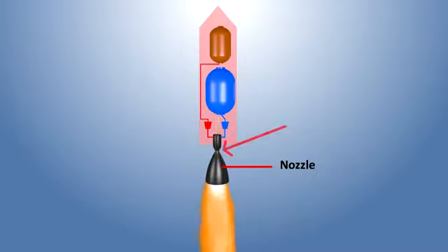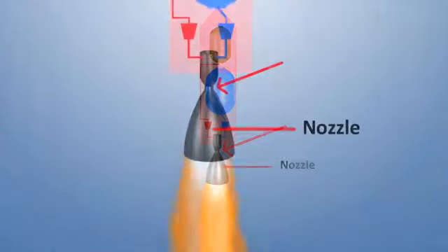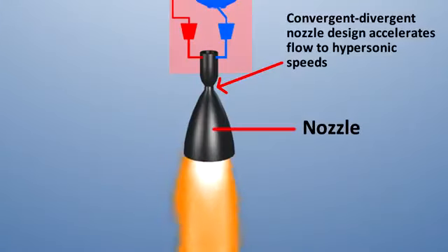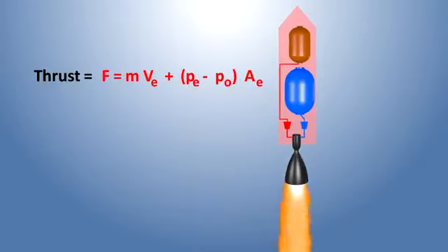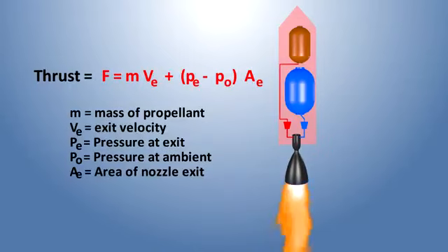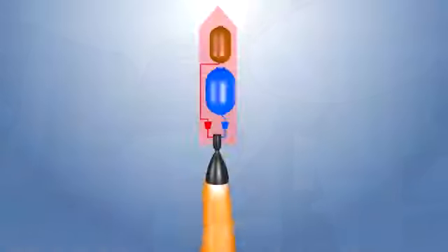The shape of the nozzle of the rocket is designed to increase the velocity of the exhaust gases further to increase its thrust. Highest thrust is achieved when the mass flow rate of the fuel and exit velocity of the propellant is high, according to this equation. The fuel has to be delivered at high volume and pressure to get the thrust required for lift. This pressure is powered by fuel pumps that boost the pressure of the gases before entering the combustion chamber.